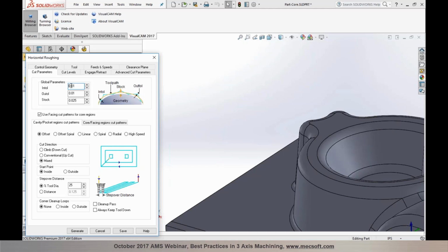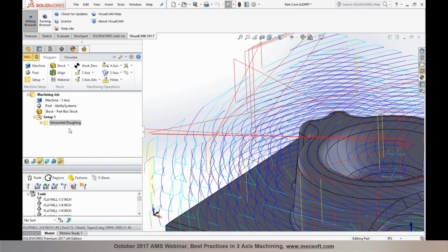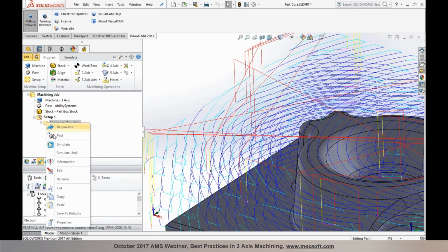If you have a slacker tolerance, you will notice that the toolpaths generated have larger chord segments. The tighter the tolerance, the more go-to motions you will end up with, which means more points between each motion.